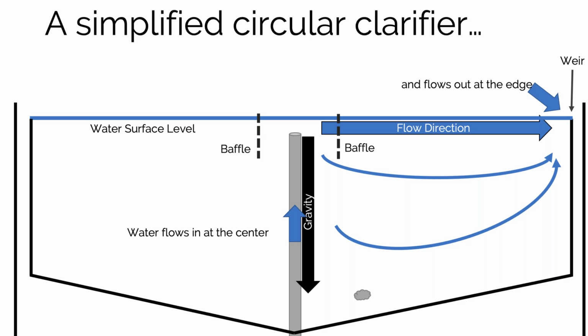So, there's a flow element here, there's a specific gravity element at work here. And of course, we can't change gravity, but we can adjust the detention time by changing the flow, basically changing how fast water is moving through this process. And you can use your basic understanding of processes like this to sort of calculate in your mind what answers are likely to be reasonable. Is this a process that's going to happen in minutes or in hours or in days?